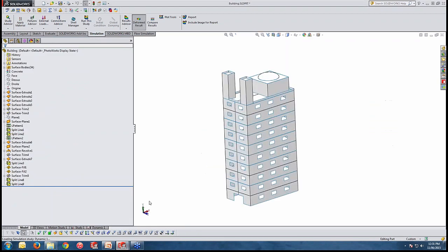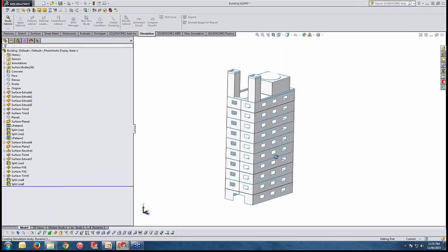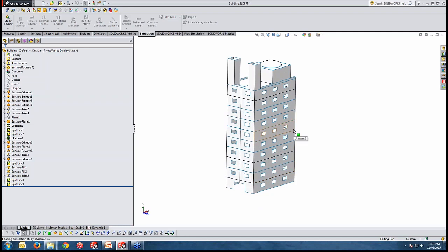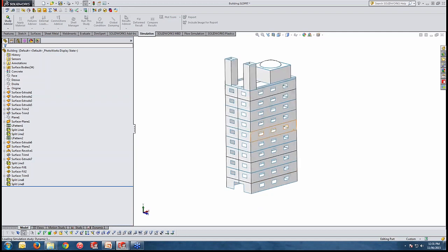In the next case, we are considering a building. Well, it is subjected to, let's say, an earthquake. You can see one good thing we have is that shell elements, or surface CAD geometry, can be simply used in our linear dynamic analysis. That could save you a lot of time by simplifying your geometry with shells rather than solid elements, which take a long time to solve.